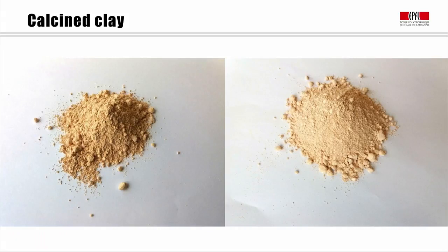Depending on the other materials that are present in the clay, the colour of the clay can change over the whole spectrum from white to a reddish colour if there's a lot of iron oxides present. You can actually control the colour that comes out in the end by the conditions of oxidation and reduction in the kiln.